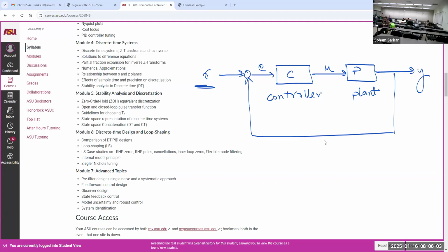All this while I was talking about linearized procedures. You will use a linearization procedure to take a nonlinear system and find the transfer function out of it. There are alternate procedures like system identification. You can take the input and output of a system and find the transfer function from it, because not all systems can be realized mathematically via nonlinear equations.